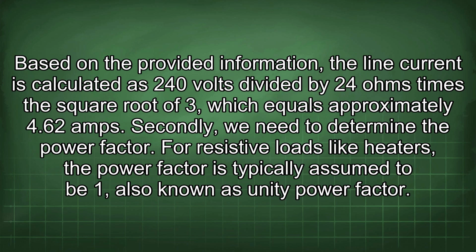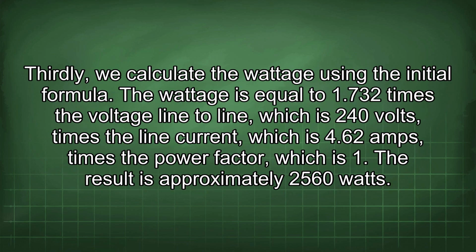Secondly, we need to determine the power factor. For resistive loads like heaters, the power factor is typically assumed to be 1, also known as unity power factor. Thirdly, we calculate the wattage using the initial formula.